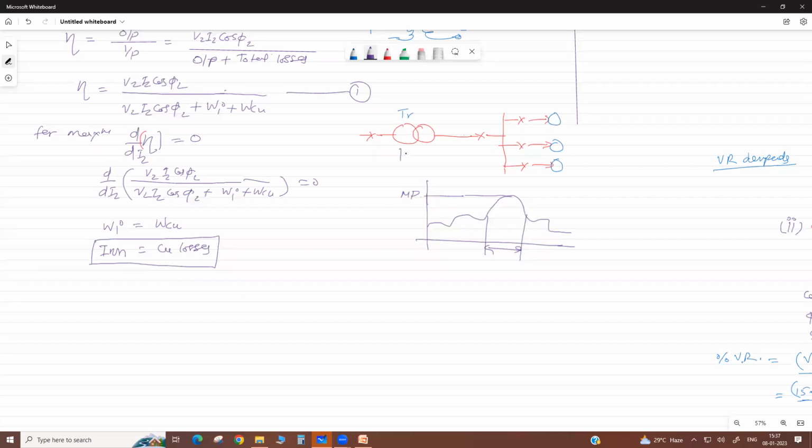This has like a 100 kVA transformer. But this 100 kVA load is not there all the time. There may be 50, 70, then it is 90. Most of the time it is your base load only, not a peak load. Therefore, as you know, at half load, that is at partial load, the efficiency is low.